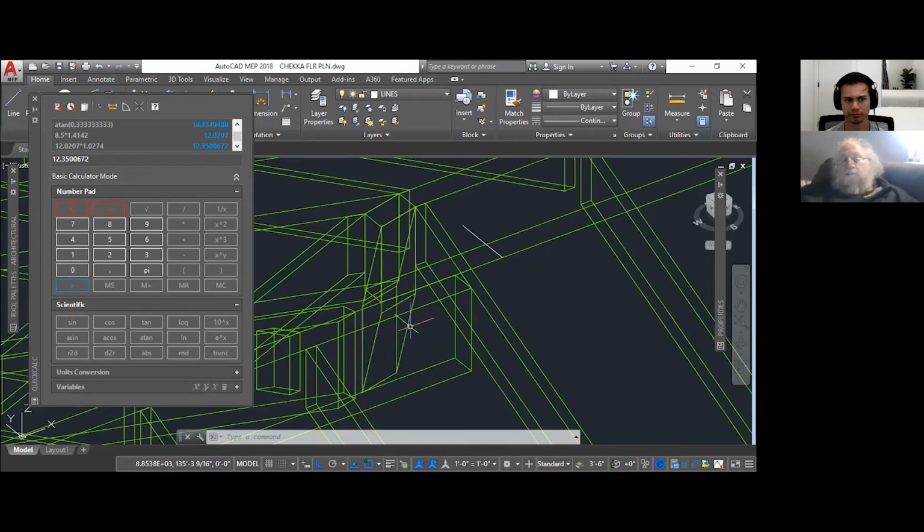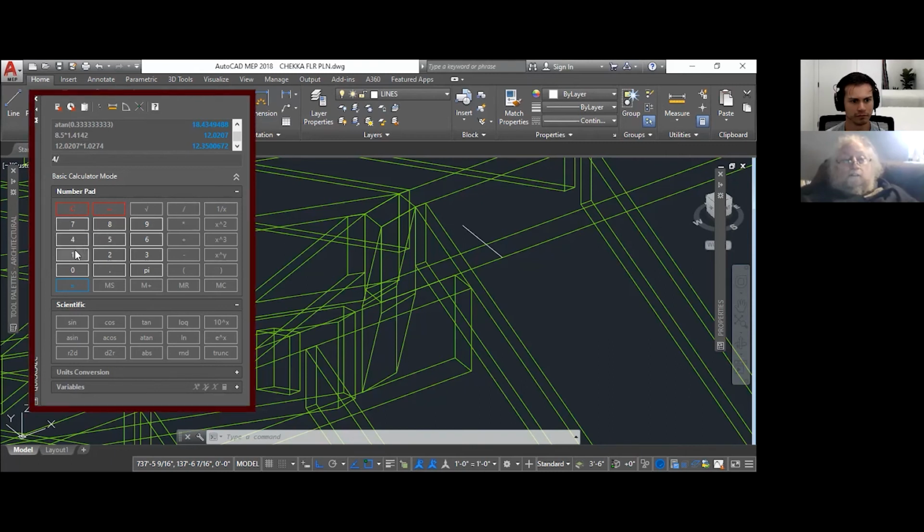as your rise. Now, how did I come up with the number 1.0274? Well, I took 4 and I divided it by 16.97, and that gave me a decimal that I could take the tangent to the -1 power of, and it gave me 13.263 degrees. That's what this little hip rises at, 13.263 degrees.